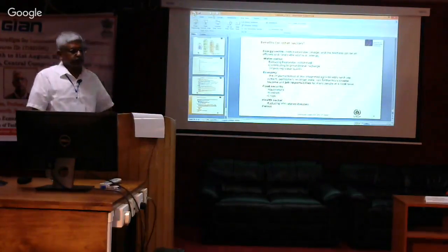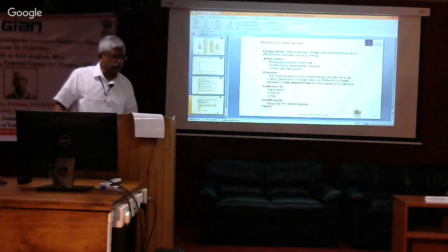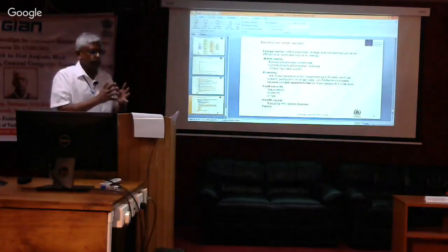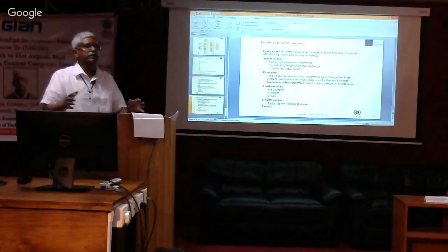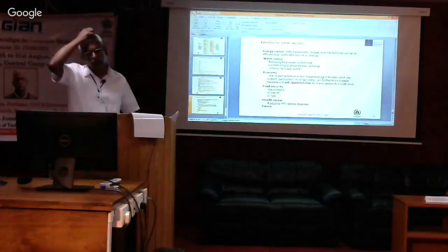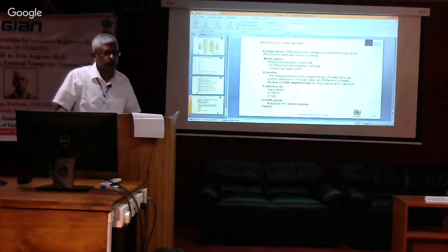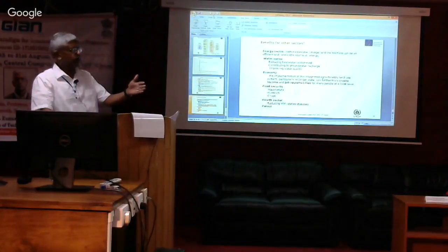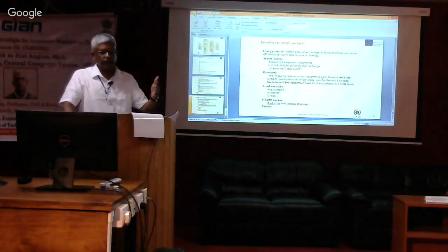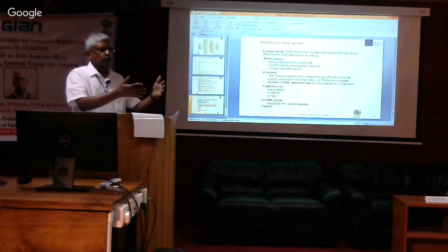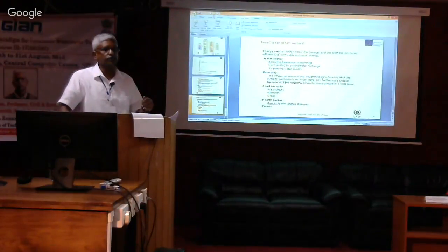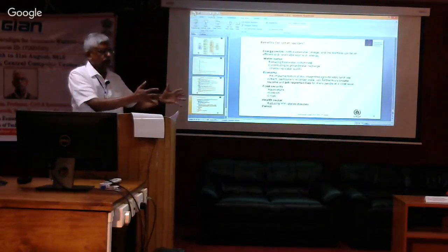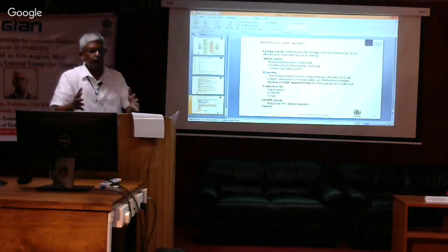The technical definition of a decentralized treatment is that the treatment is at source. Now, that source could be as small as an individual residence, which is what we call typically septic tank systems. Of course, that is a little primitive. In a typical septic tank system, that means you don't have access to a wastewater treatment plant, a sewer as we call it. You get this wastewater from your house, it comes into a septic tank.